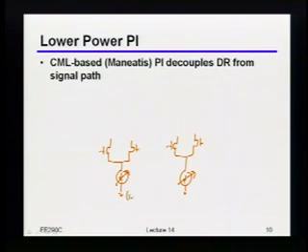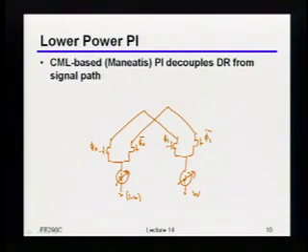So this is where you do the 1 minus W. This is where you do the W. Let's say that that's phi 0 bar, phi 1 bar. And then, of course, I just tie those outputs together, and I'm going to be dumping them into some kind of load. Now, in the simplest case, you'd be dumping this thing into a resistive load. But unfortunately, remember, I want to run this thing over a really wide range of data rates.